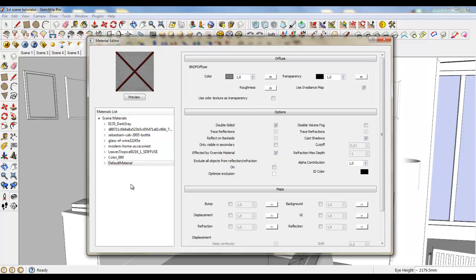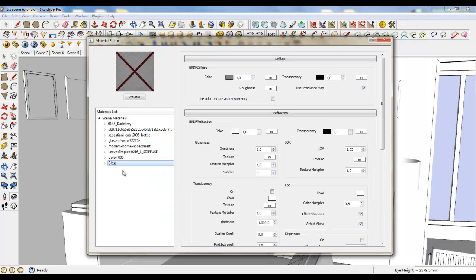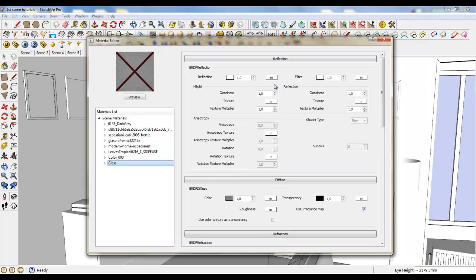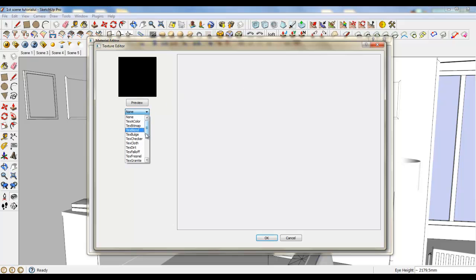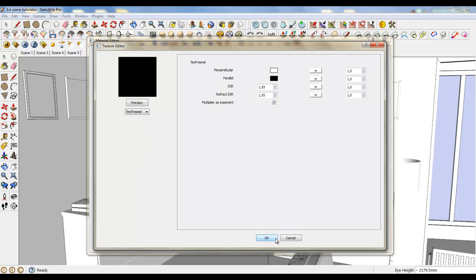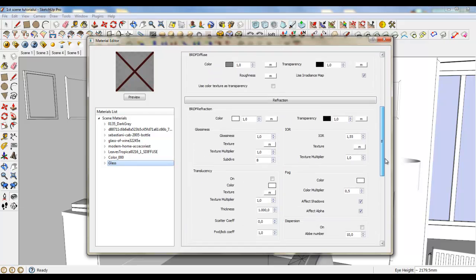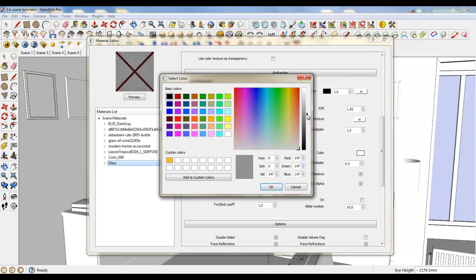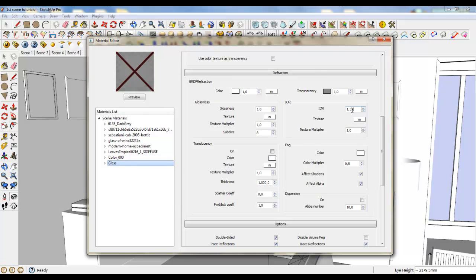Also we need some transparency, so we are going to have a refraction map and also reflection map. So leave everything, just add a Fresnel map. Everything is okay. Now go to refraction and turn on translucency. Don't turn on, just leave everything and make this something about the middle, and also 1.517, and we have a glass material.